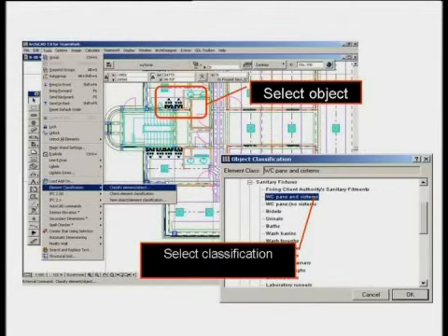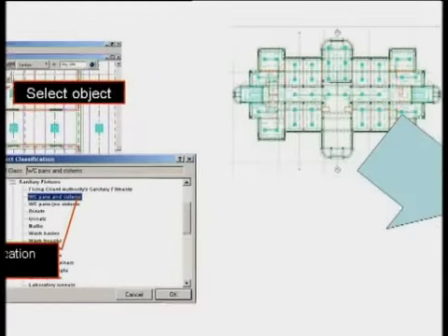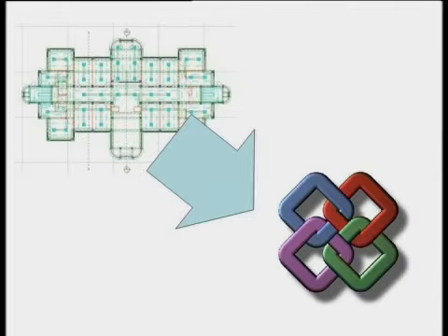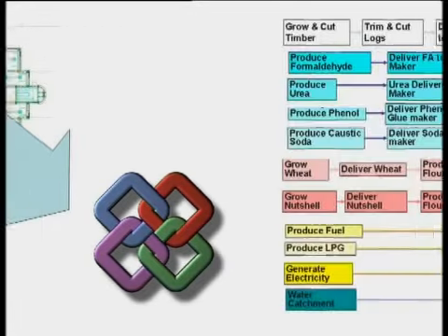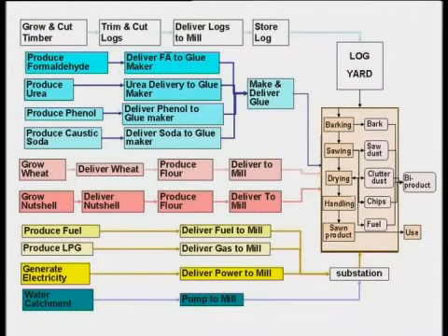These rules enable a detailed material breakdown to be calculated for each building element. Once tagged, the model is exported via an IFC file, which is the internationally accepted standard for 3D CAD model data transfer. The essential data for calculating environmental impacts of building materials is a life cycle inventory of the common building products used in constructing a commercial building.